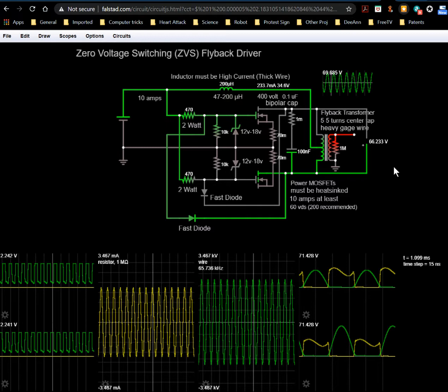Interestingly enough, the inductance will increase if you put something made of iron, something magnetic inside of it, like steel. The inductance will go up quite a bit. But if you put something aluminum in there, the inductance will actually go down. It's interesting because aluminum's diamagnetic.